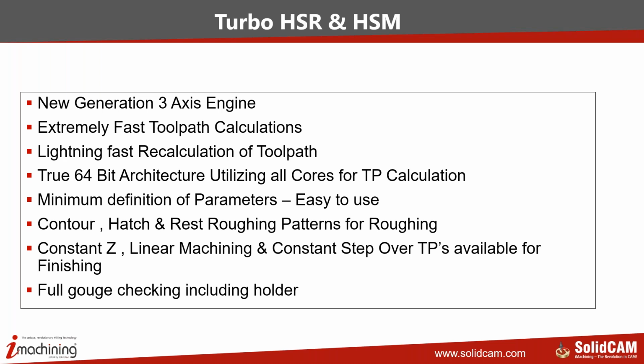The parameter definition in creating toolpaths is bare minimum. There is not much that is expected from the user, making it very easy to learn and to use. And we have a set of toolpath strategies like contour, hatch, and rest roughing patterns for roughing, and for finishing, constant Z, linear, and constant step over toolpaths, including rest finishing.